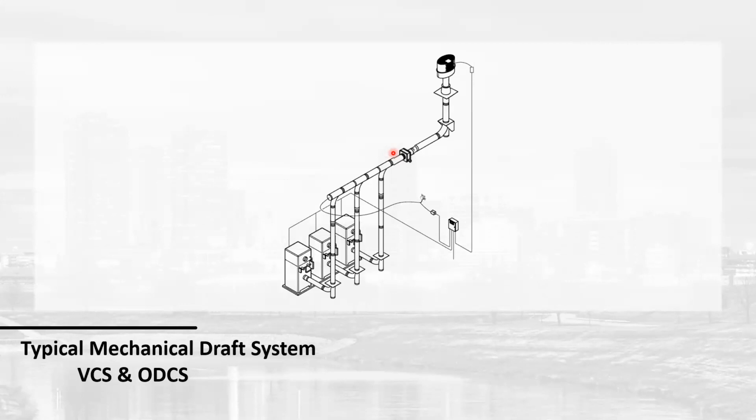Many times we'll use this damper also as a trim damper for the fan. My fan has a 10-to-1 turn down. If you have 6 boilers with a 10-to-1 turn down, your system is now a 60-to-1 turn down. My fan just can't drop low enough to maintain the pressures that are needed. So it will mechanically overdraft the system. So we start to choke that off with our damper. Best part is it works with a single controller, so that it's not trying to fight each other at all times.